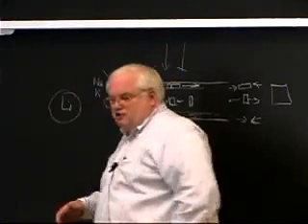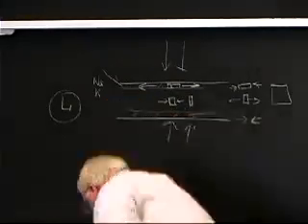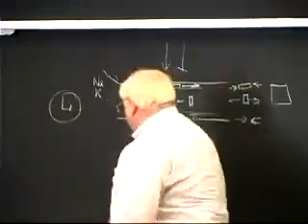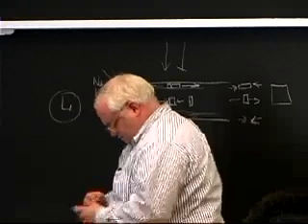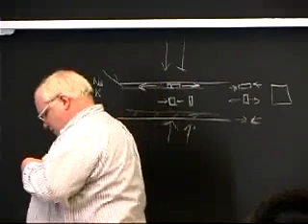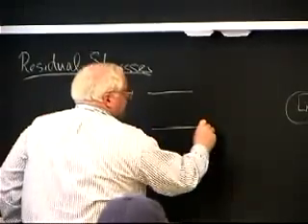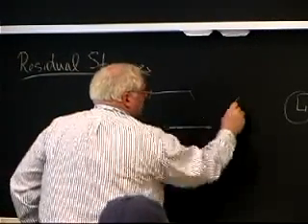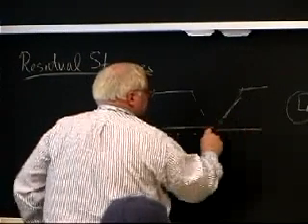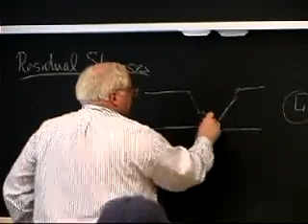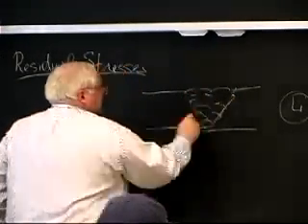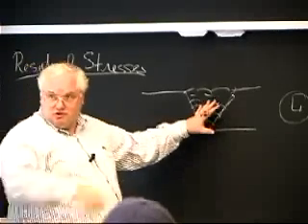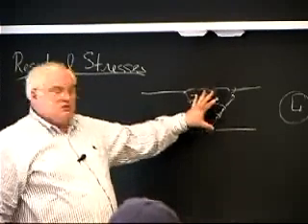Now, residual stresses occur in welding all the time. In fact, the problem is that in welding, if I have a fairly thick section weld, let's say it's a couple of inches thick, and I put a weld in here, and I put another pass, another pass, another pass, what will happen is this metal shrinks because there's about a 4% volume change when the metal solidifies.